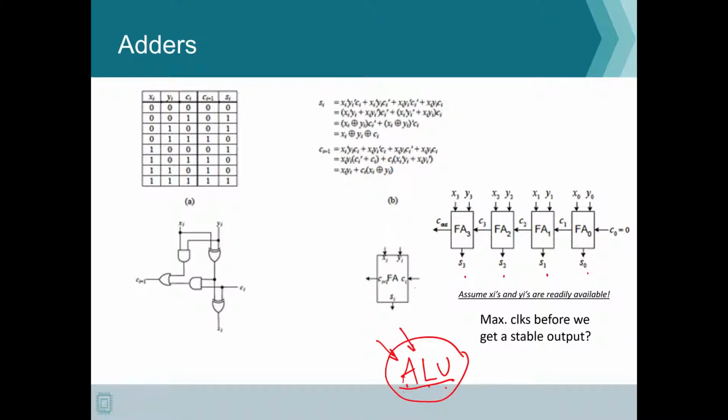And this particular configuration is actually called a ripple carry adder, because in order for this sum S1 to be created, it actually needs the carry out from the previous stage, and similarly for S3 to be calculated, it actually needs this carry, which is dependent on this carry, which is dependent on this carry, and so on.